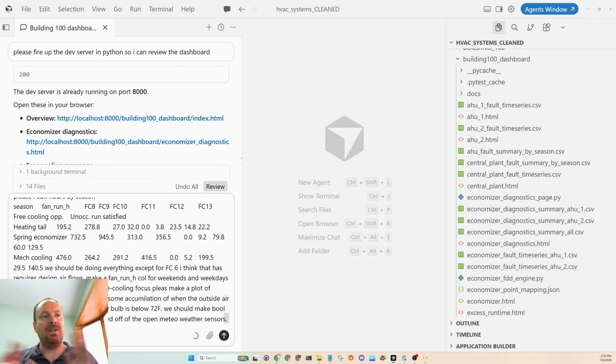Maybe someday we could do a deeper dive on what that looks like on a psychrometric chart. But basically, in shoulder seasons, when the air is relatively dry, the dew point is very low. As long as the dew point is very low, and anything below 60 is low, and as long as the dry bulb doesn't increase above a zone comfort of 72 degree dry bulb, we can bring 100% outside air into the building.